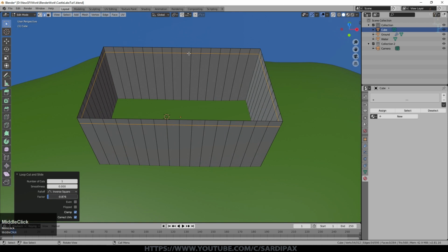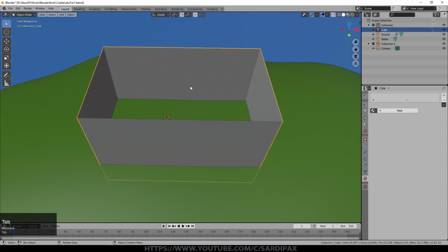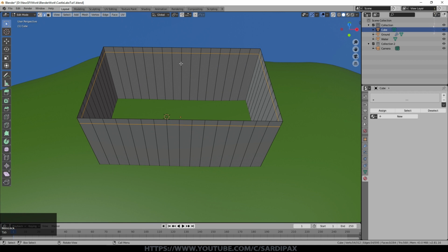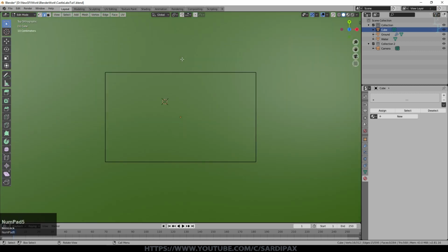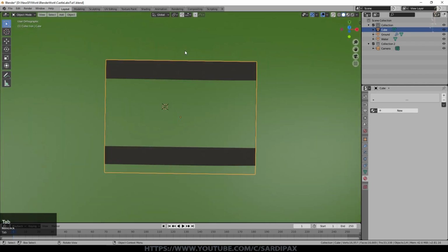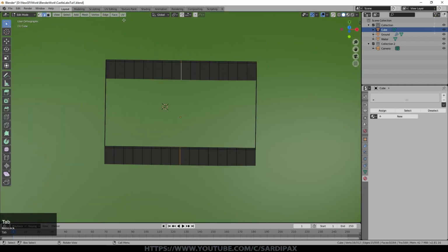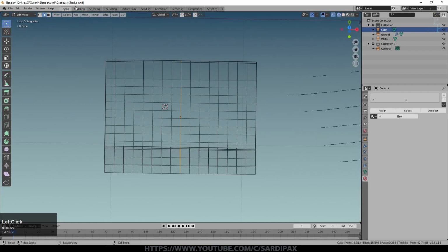And at this point, rather than creating the whole thing, let's cut it in half. I've got a base underneath here, so that's joining these edge loops. So from about there, that's about right. I'm going to go into orthographic view as well, because it makes things a little simpler. And at this point, wireframe too.